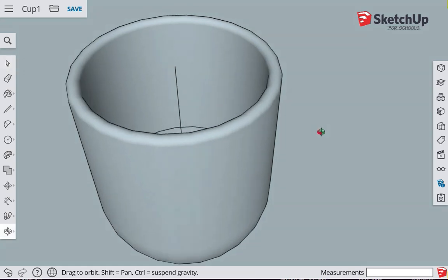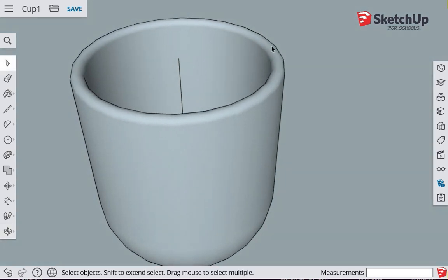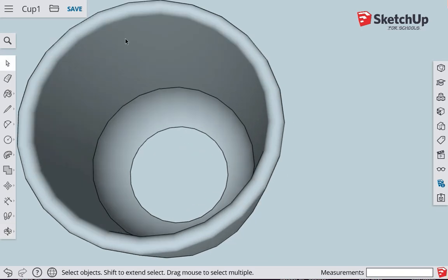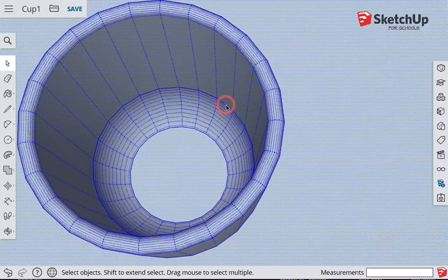So it worked at that time. So apparently that time it wasn't part of the geometry of the circle by being right on the top edge. It just was something to follow. So I'll click this center line, I'll click delete, and we'll take a look. Now the other lines that you see here, they're just at the transitions between, well, this is an outside line that describes the outside, and this defines where the cup goes straight down and it starts to do a curve. This is where it stops doing a curve and starts to do a flat. These lines aren't different segments of our cup, or are they? So can I delete this line? No, I don't want that.